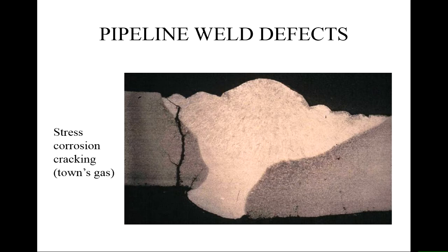What else do we have here? Stress corrosion cracking. Now, as the name suggests, for stress corrosion cracking to occur, you must have certain elements there. First, stress. There must be some stress present, which can be residual stresses, present in our case in the heat affected zone.